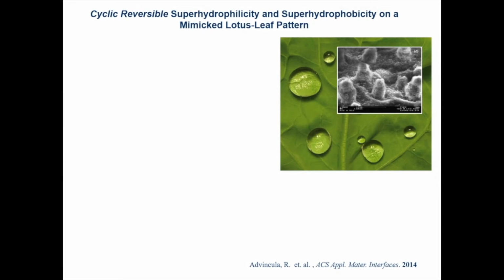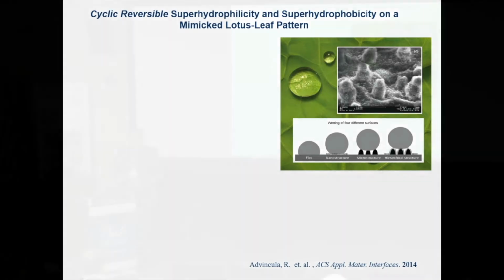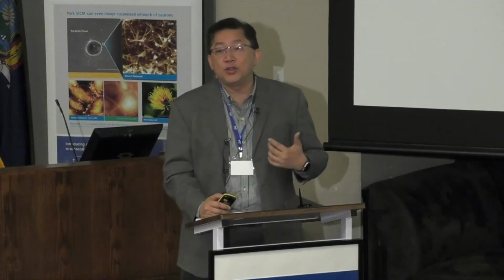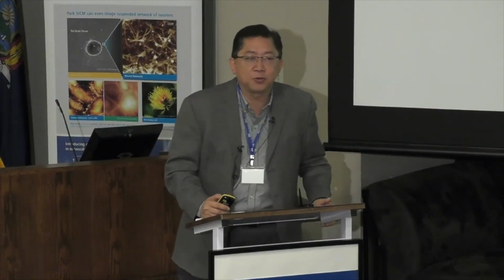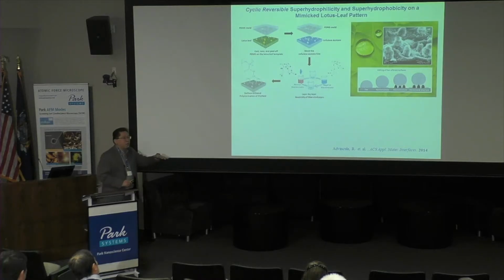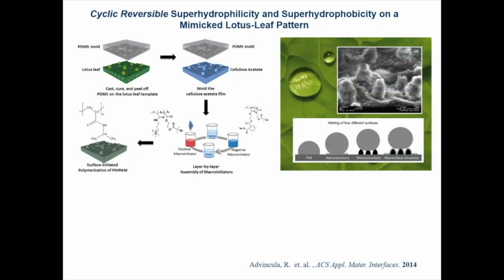And to get this into a non-wetting state, you basically take advantage of what we call the Cassie-Baxter approach, which is you trap air, and then you form a droplet because of the failure to form a continuous line tension. So if you try to do this, and many people have done, using lithography, non-lithography, we're actually doing 3D printing. We're 3D printing super hydrophobic surfaces these days, and we can also template them. So if we use a silicone mold, we basically put the silicone on top and then copy it. We take this copy and then we register it so that we can grow a polymer brush.